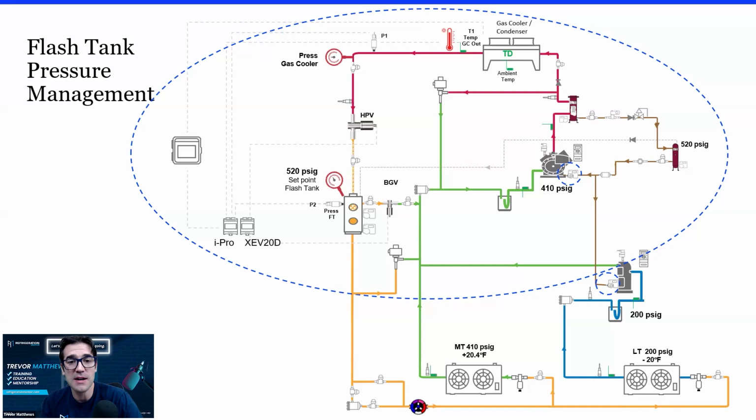And you've got to think outside the box. You've got to look at those trend graphs. Look at your suction, just like Andre said. If my suction is floating suction, we're normally running at 410, but we were able to get another 5 psi or 8 psi higher in my suction. But now my receiver or my oil reservoir is down to 530. There's not going to be flow.